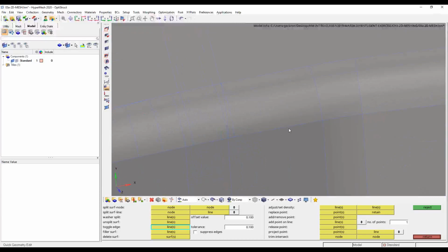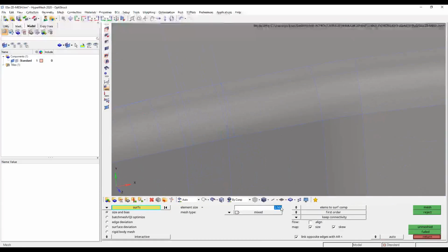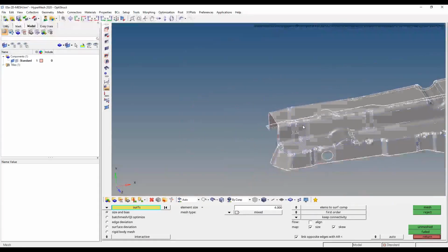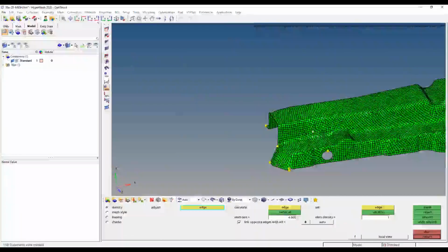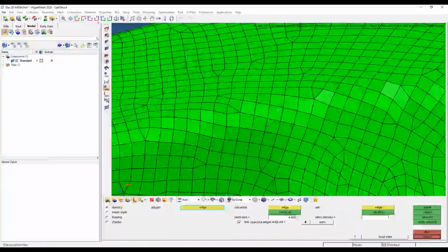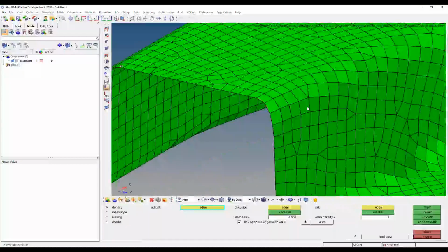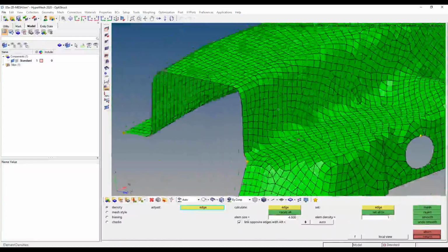Where is it curved? Where is it planar? Because now if I come in here and just mesh these new surfaces as one big smooth surface, like you're saying, yes, it's smooth, but where does a fillet start? Where does a fillet stop? Look how much definition we've lost on this mesh. That's something we really want to stay away from.